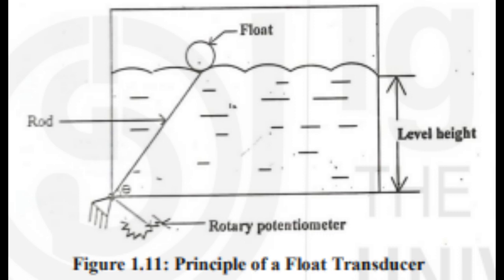The emitter is typically a light-emitting diode, and the detector is a photosensitive transistor. When light is incident on the base of the transistor, current flows from collector to emitter. As the disc rotates, the light will be alternatively blocked and allowed to pass. In the blocked state, the transistor will stop conducting.